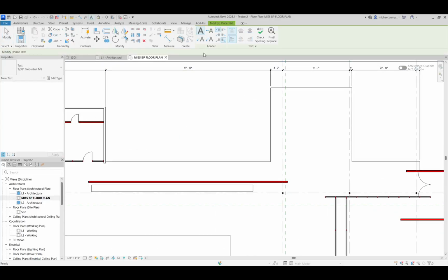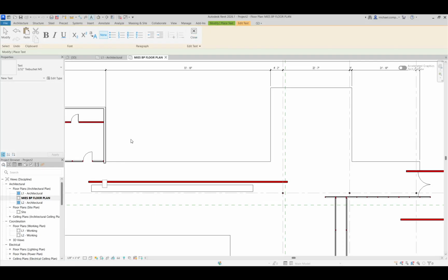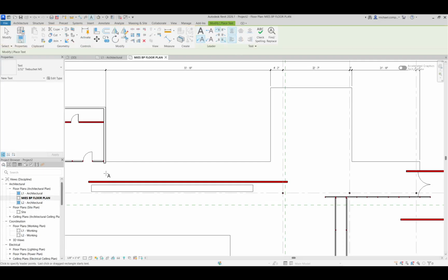The next thing I want to show you is a specific call out, right? This one is a 2-segment: you have a straight line, you have a curved leader. I like the 2 segments personally. So I'm going to click this wall. That's the start of the first. Oops, I didn't click it. There we go. This is the start of the line, so what it's pointing to.